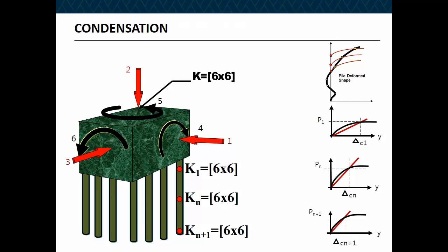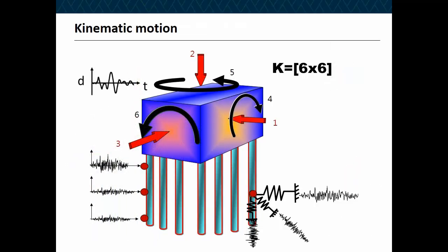And the run time was done in less than 4 hours actually. I was very surprised. And then to develop the kinematic motion as part of the substructure, like I said, you input your free field motion at every node and shake the foundation to come up with what we call a kinematic motion. It is this kinematic motion and a 6x6 matrix that will replace the foundation and not to include it in the global bridge model.